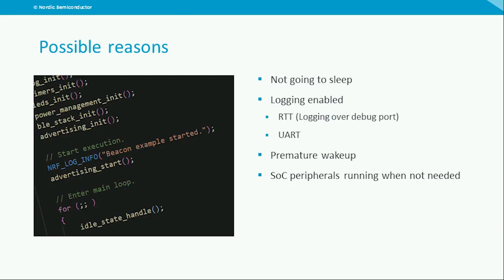With most embedded applications, a good practice is to do all the setup that needs to be done, then enter an infinite loop and let interrupt routines and hardware events do the rest of the work. This means that you will end your main function with an infinite loop that calls the _WFE instruction on the ARM core. The wait for event instruction will put the device to sleep and wait for an event to occur, meaning that when an interrupt is triggered, the device will wake up, handle the interrupt routine, and go back to sleep when done with that job.